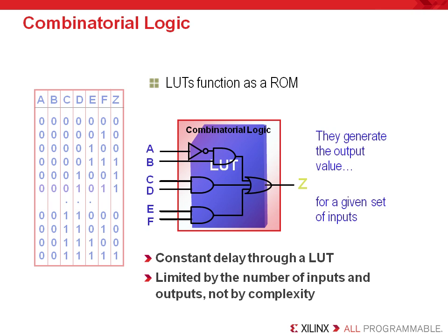While synthesis tools will optimize your combinatorial logic, one of the essential things they must do is map the combinatorial logic to the 6-input LUT. This is essential because a function of, say, 7 inputs might require a second LUT, and if optimized improperly, might add a LUT in series. This, of course, would increase the combinatorial logic delay and frequently impact system speed.